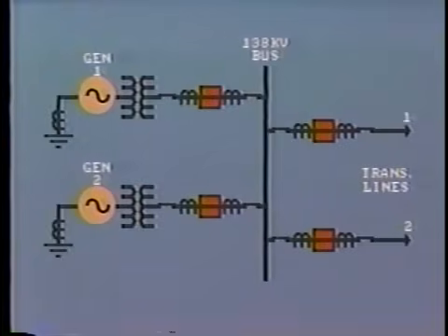Where a voltage signal is required for protection, say a directional relay or impedance relay, then the VT is normally connected directly to the bus like this.